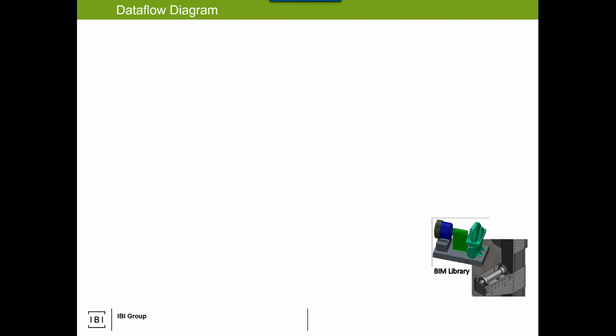It all starts with a library. There's a component library of stuff. Oftentimes people try to grab it online from vendors without quality checking the material. So we always got to be careful. The stuff we're grabbing, will it bog down our model? Does it show the right stuff? And I like this example. Do I need all those rivets and all that stuff? Probably not. This is a very generic pump, I think it is, if I remember.